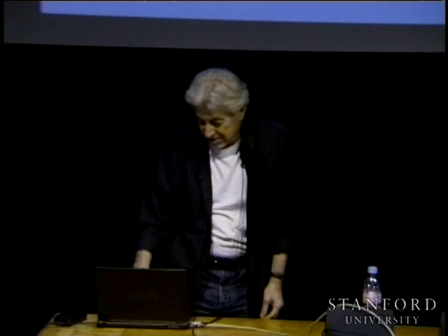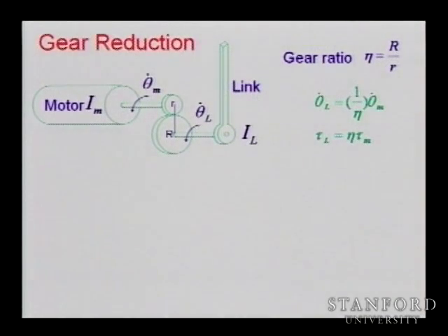So the gear ratio is reducing the speed. The link is going slower. So how much slower? 1 time, 2, twice, 3? He said like 2. Looks like 2. Yeah, it is 2. I was worried. Okay. So the gear ratio is really R divided by the other R, the smaller R. So that's your gear ratio. And the link speed is smaller by that ratio than the speed of the motor, right?